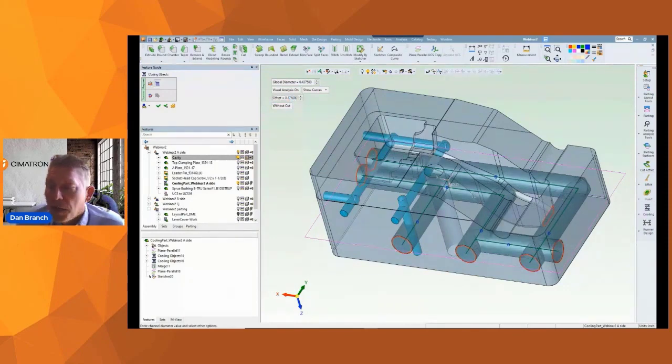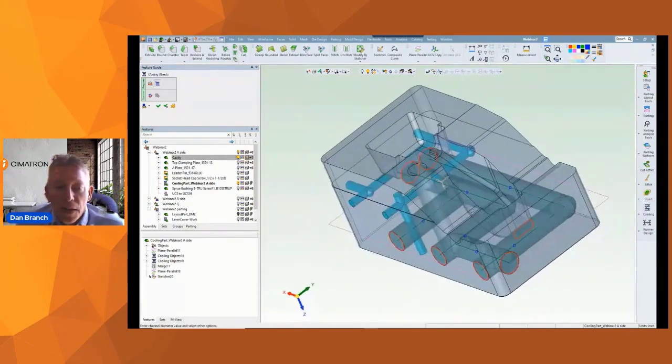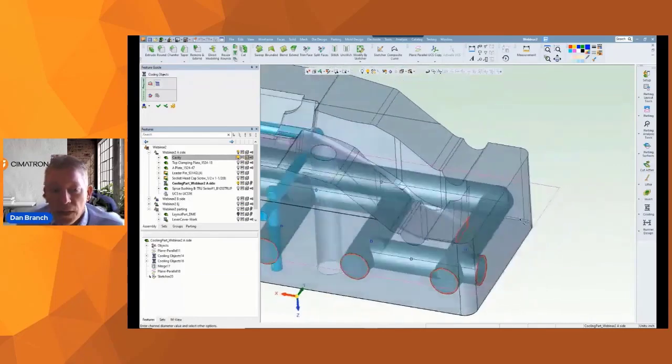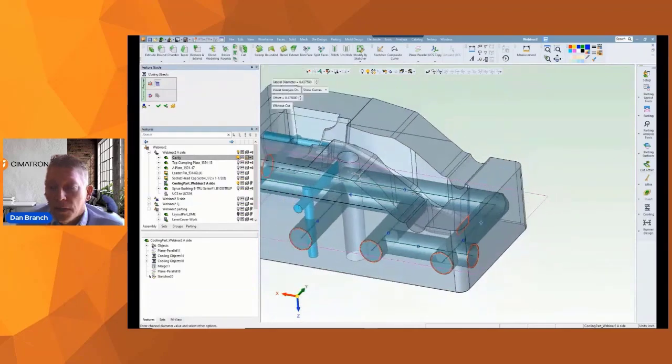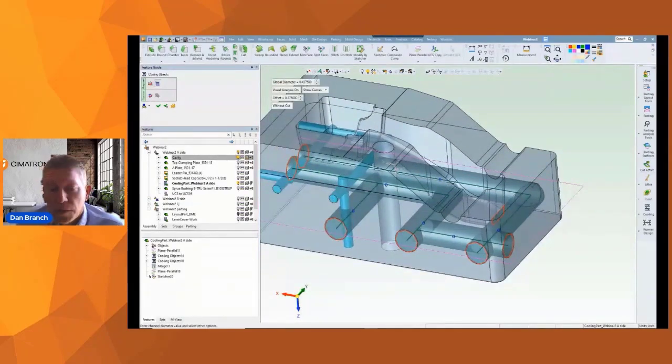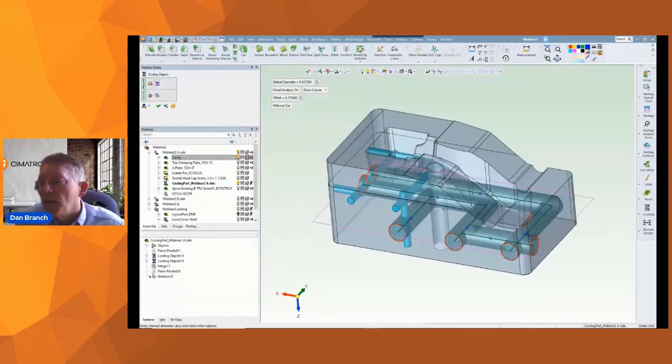So at a 1/4 inch, I'm not seeing any other collision, but if I move that up to 3/8, now I do see a pretty big area of part geometry that touches. So what that's telling me is if 3/8 is my desired safety distance, I do have to move this end water line farther away.